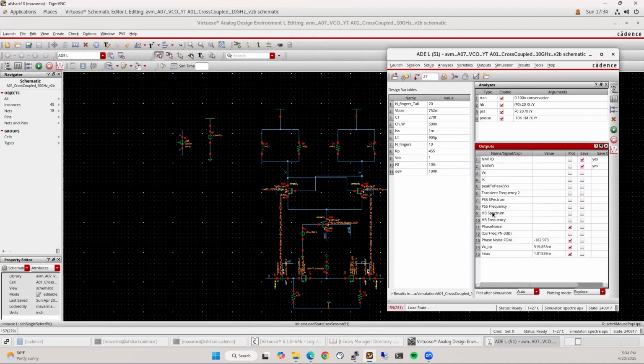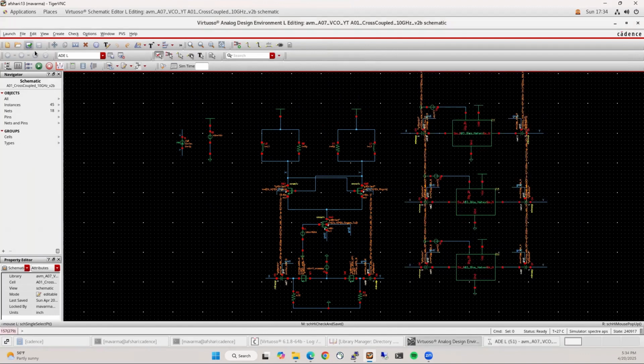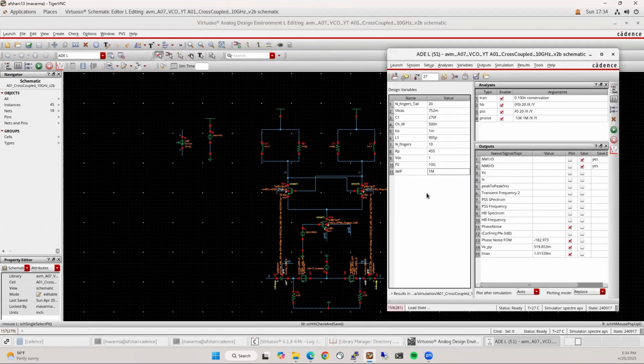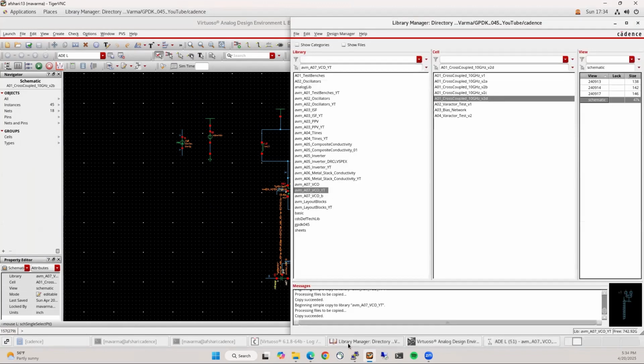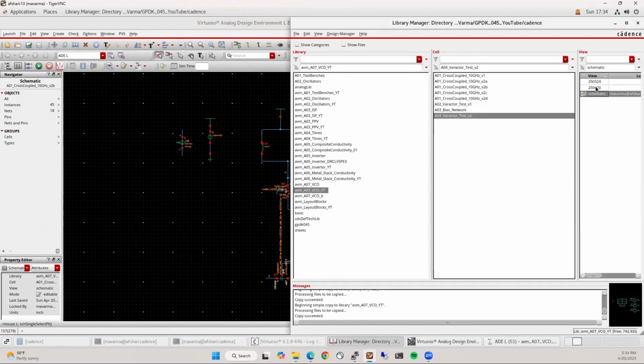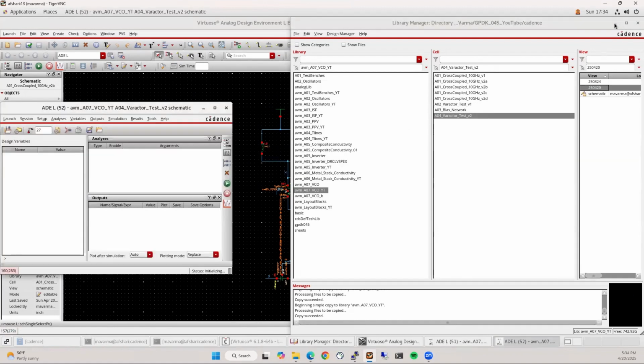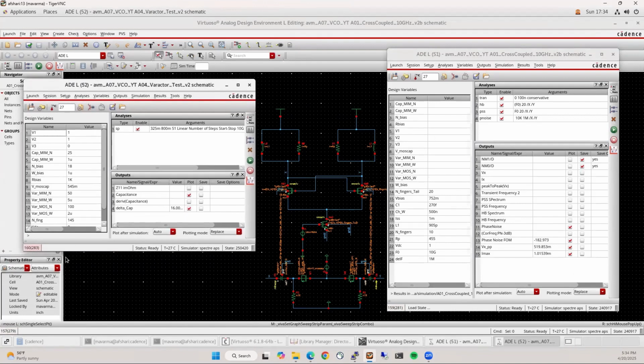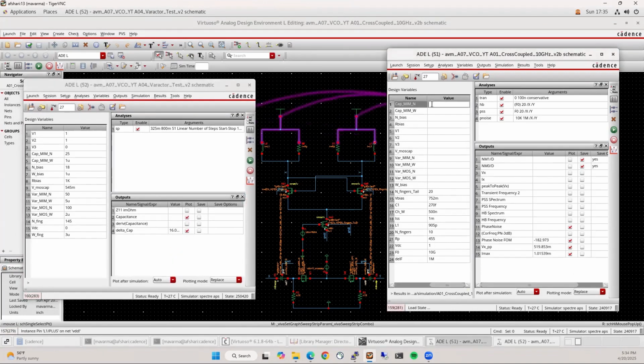Yeah, the phase noise form was around -180, but that was at 100 kilohertz offset. Let's make it 1 megahertz. And then we also want to include all the other new variables which we added in, right? So I don't remember these values. Let me quickly fill them in from what we just designed, which is this one. Okay, cap min 55, width is 1 micron, and bias is 18, our bias 1K.